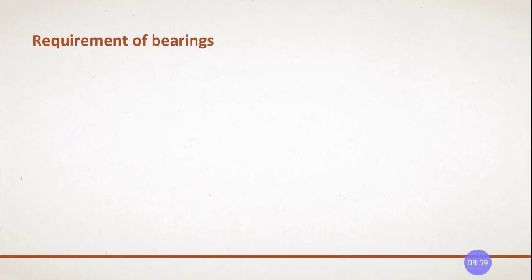These are the functions of the what? Transferring the load to the larger area, then taking the vertical deflections, and due to the vertical deflections, they also bear the moments and angular moments. They also bear the longitudinal movements due to the application of brakes and temperature changes, right? These are the functions of the bearings plate of the bridge.